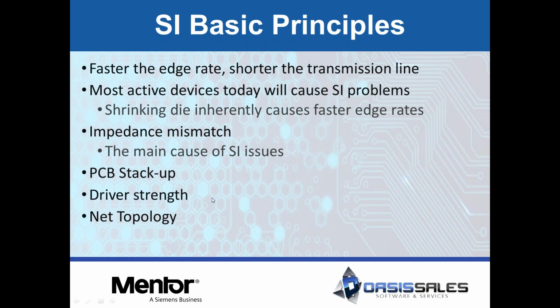And that can increase the signal integrity issues that you might be having. So a lot of this stuff you can look at in the specifications, make sure you're checking out that data, because you can very simply do some testing real quick by downloading IBIS models to check it within HyperLynx or another signal integrity tool.